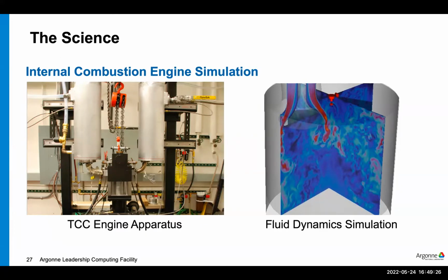So my colleagues and I in the Energy Systems Division at ANL wanted to understand some common turbulent modes or features that appear during a full cycle of the engine operation. And this was needed to help us understand how such features impact cycle-to-cycle variability during normal engine operation, which commonly occurs in typical passenger vehicles. And so the simulation that we did was actually a large eddy simulation.